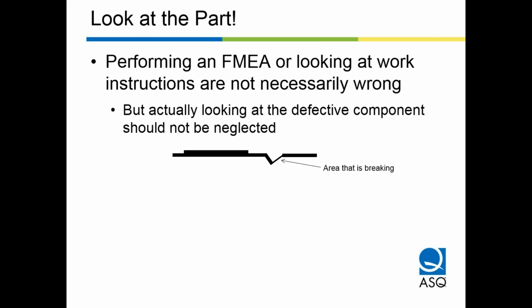I was talking about empiricism. First you do a failure modes and effects analysis, and then you do a quality function deployment. Quality function deployment is generally done when you're designing the product or process. Shouldn't you look at the part? And our root cause analysis needs to be empirical, was my response. And he told me the quality function deployment is empirical. You need to go into production and look at the work instructions, which I think is not always possible if you're just coming up with a design concept when you're using a QFD.